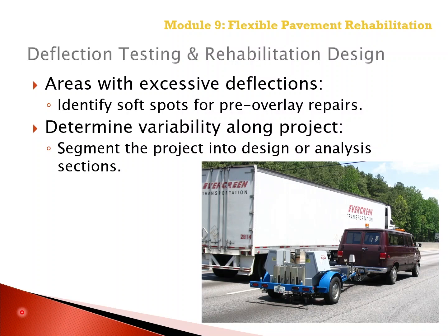Also from deflection testing, determining the variability or the amount of variation along a project. In addition, deflection testing can also be used to segment the project into design or analysis sections.